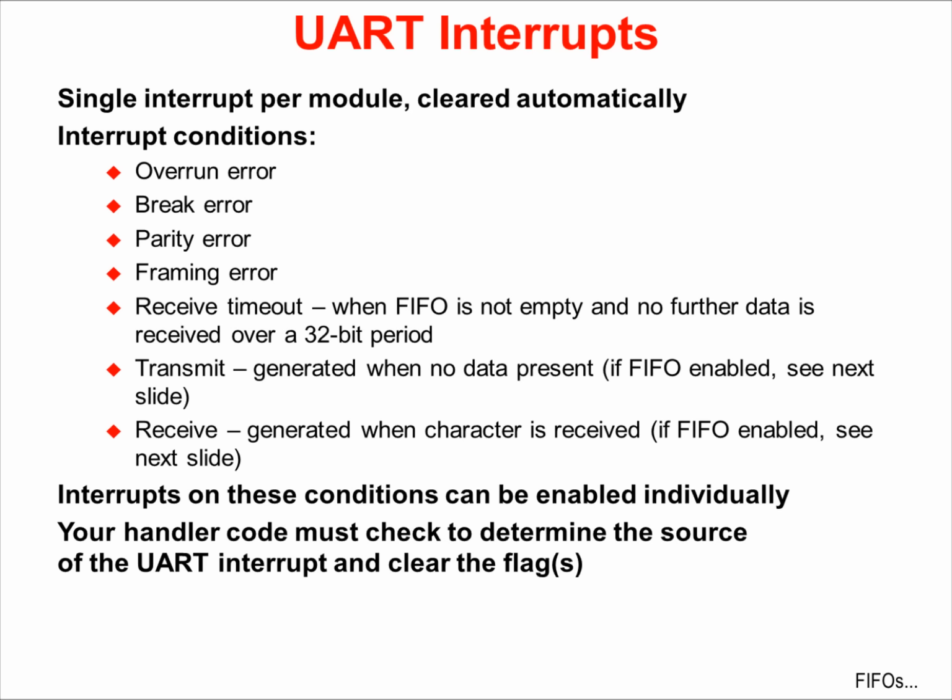Since these conditions are ORed into a single interrupt to the CPU, the handler code must check to determine which of these conditions triggered the interrupt and clear the appropriate flags.